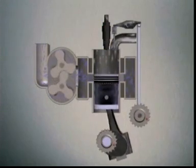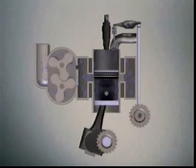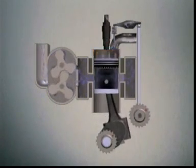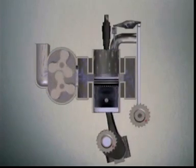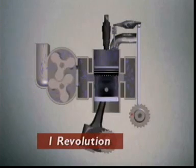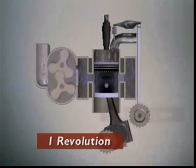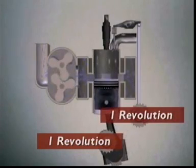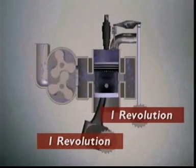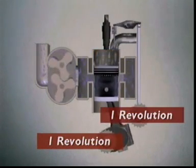This is a two-stroke diesel engine. How many revolutions does the crankshaft make in one cycle, from intake, compression, ignition, power to exhaust? It makes one revolution. During that revolution, the valve opens and closes once. The camshaft makes one revolution too. Camshaft and crankshaft must rotate at the same speed. The gears must be the same size.